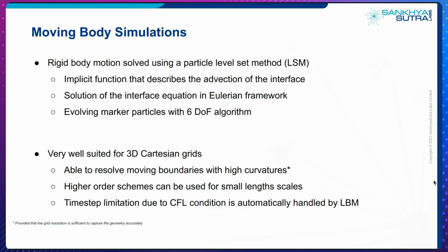And the time step size limitation due to the CFL condition is automatically handled by LBM. So even that is not a problem when it comes to level set methods, because that is usually something that is a pain point when it comes to finite volume simulations. So the CFL condition of 1 is automatically maintained by LBM, and this means that you don't have any limitations.